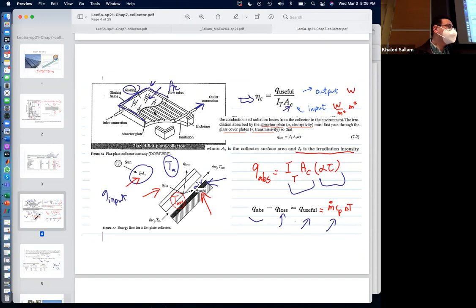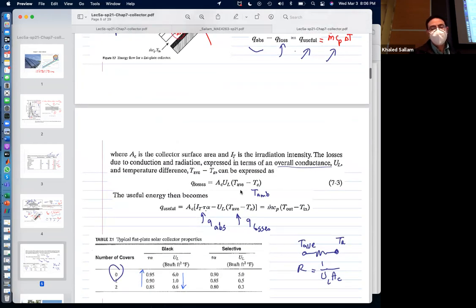So the temperature in the middle is a good representation of the temperature inside. T average. The only problem with T average is that we don't really know it. When you are picking that heater in your calculation, you just know your T inlet, but you don't really know yet how hot it will get. So you don't know T outlet yet, and therefore you don't know T average yet. You will see that in the next page or so. I would basically say let's do it over T inlet instead. But T average is really a much better indication of the temperature of the plate, right?